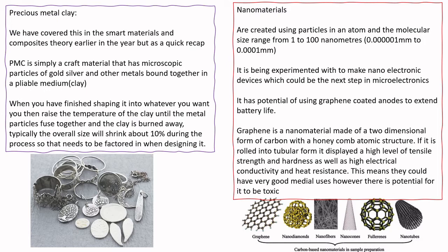Typically, because you're removing the medium, the clay, it ends up shrinking by about 10%. So when you're designing and making it, you need to factor that in because it does shrink.